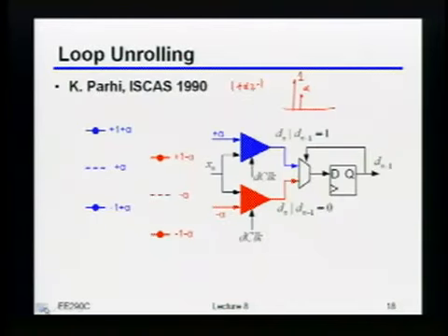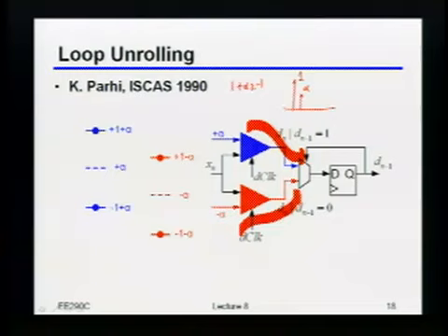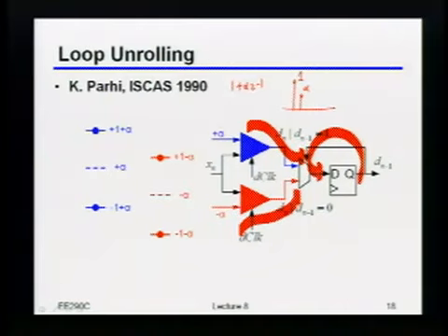But basically, it turns out that the delay of the comparator, as long as this forward path is not the critical one, you're somewhat insensitive to it because you're going to be getting a delay from the comparator on the other way. So as long as they arrive at roughly the same time, then as long as this forward path isn't the critical one, they don't really eat into this feedback path. That's kind of what it comes down to. Again, that's under the assumption that the feedback path is the critical one, not the forward one, which may or may not be the case.